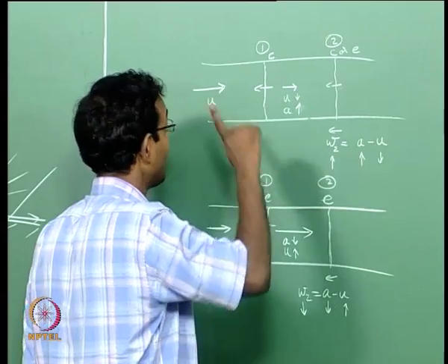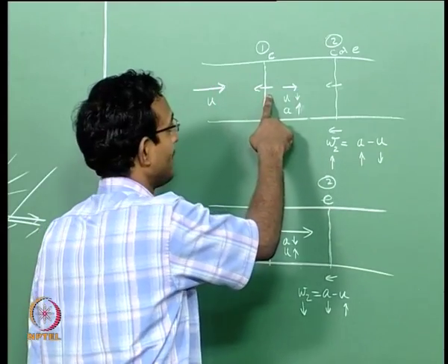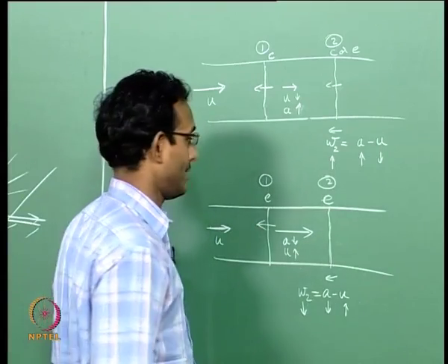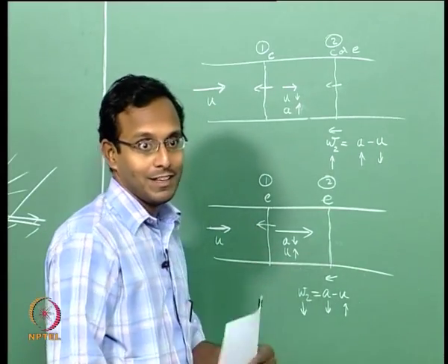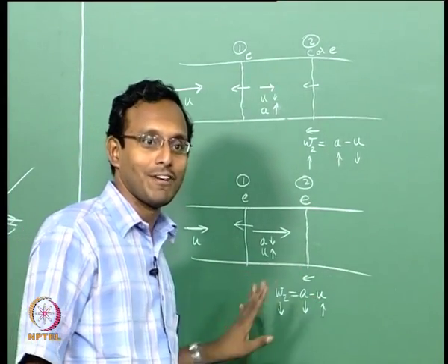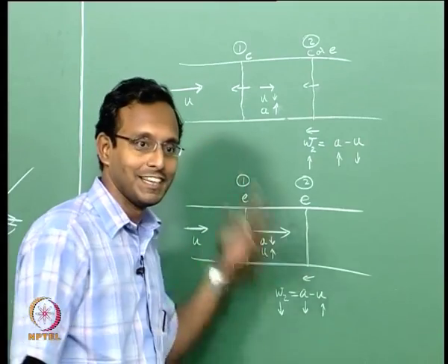If the first wave is compression wave, then I am going to say that the second wave will be accelerated. Okay. This is the reason why compression waves come together to form a shock and expansion waves go away and form a fan. Okay. The reason is sitting inside here.